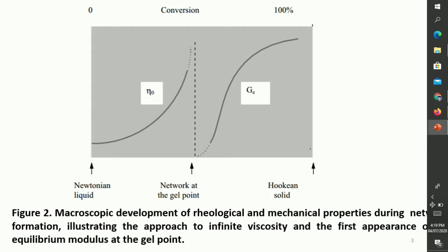The sample will require a support such as a metal shim, glass fabric, or wire mesh. These are the three supports that a sample needs for the DMA analysis. The first one is the metal shim, the second one is glass fabric, and the third one is wire mesh.